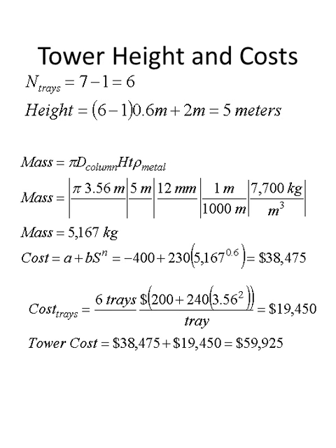$38,500. For our trays, we have 6 of those, and knowing the diameter of the tray, we can calculate the cost per tray. And substituting that into the appropriate equation, we would find that the cost of the trays would be $19,450, and the total tower cost, not including the reboiler, condenser, or preheater, is slightly less than $60,000.